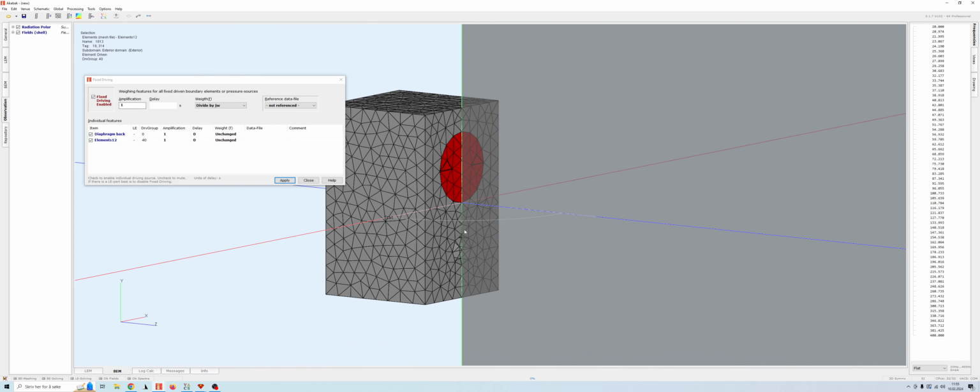And the problem with this is that it means they're moving in a push-push configuration rather than a push-pull configuration, which is what an actual driver does. When the outside moves out, the inside moves in, right? So we have to set the amplification here on the back diaphragm to -1.